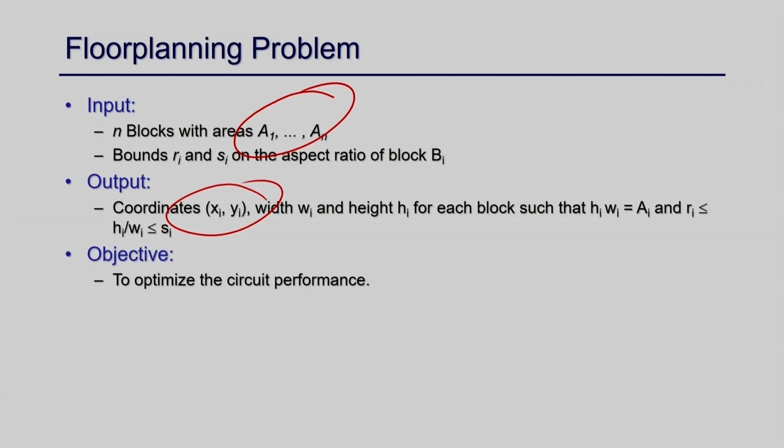There may be a little bit of movement of the blocks so that your total wire length is minimum, or you can also reduce your total area. But after placement, the position of each block is finalized, and then you cannot have any other change. The only thing to be done then is the actual making of the physical interconnections, right.